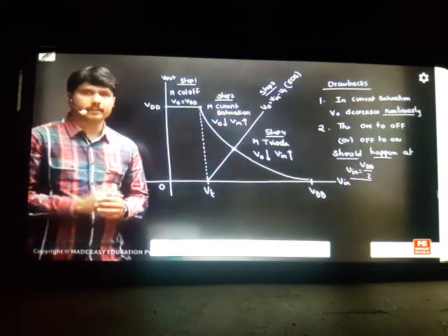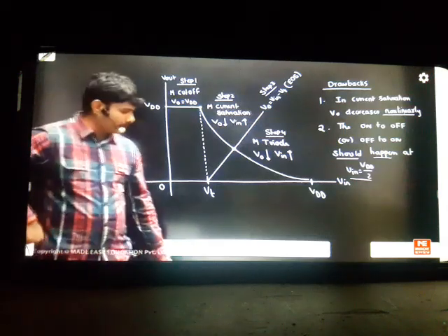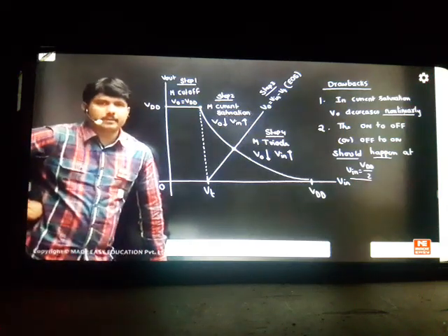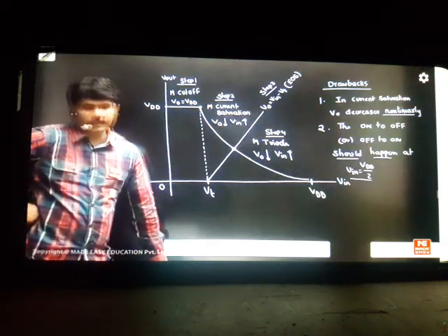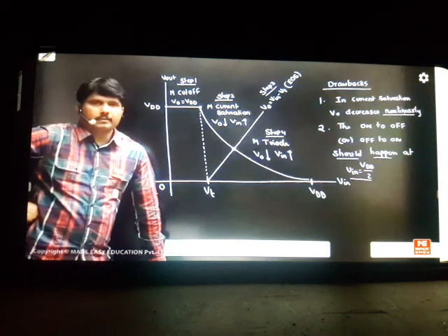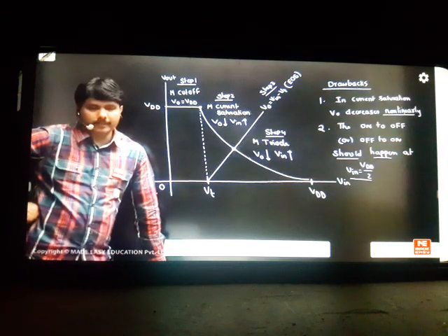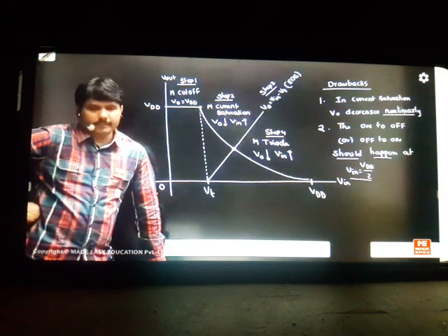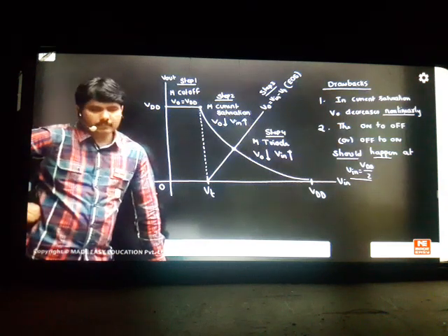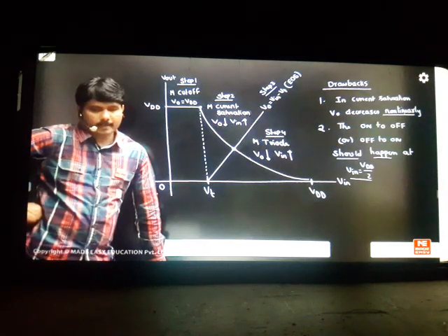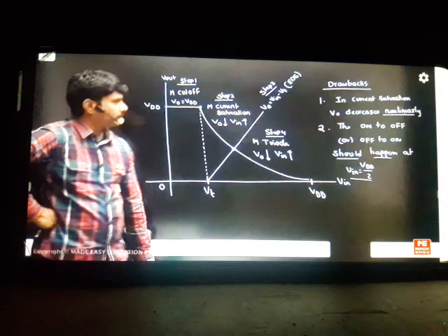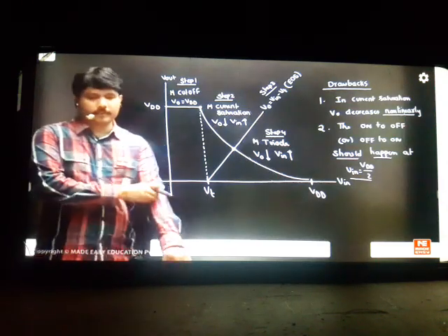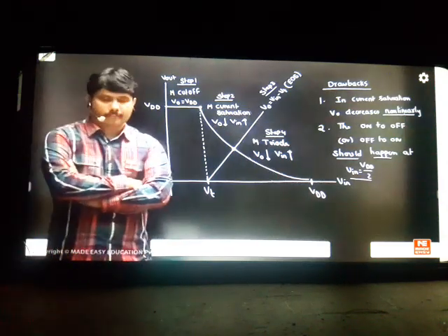Nicely, we will now understand the second step, called the NMOS inverter with active loads. That means we are removing the idea of passive loads. Now we are keeping a transistor in place of a resistor load. What happens? Then we'll see the next idea. In place of keeping resistors, today we'll keep transistors. Is there any better improvement that will come in the graph? Let us observe it. It is easy now to understand because the main concept is ready. So take the graph properly. This is about my first inverter design, called NMOS inverter with passive load.